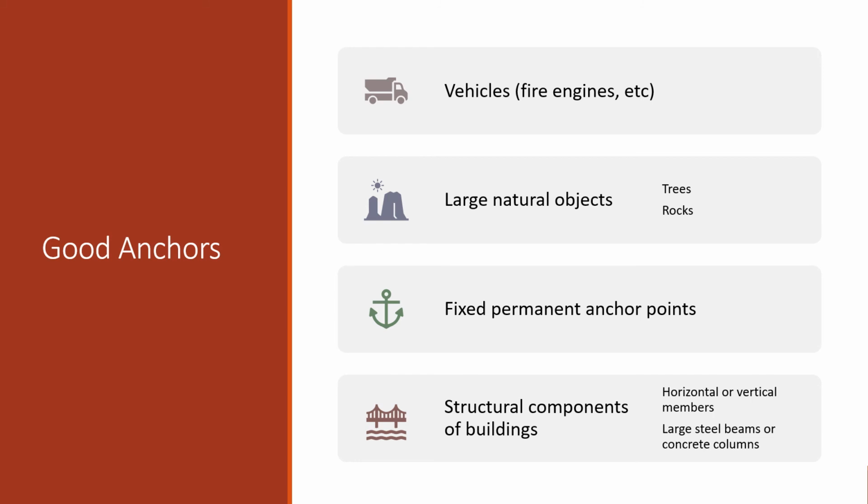Be careful with these, though. Make sure it's a real structural component. Guardrails to keep people from falling over ledges are not structural. Don't use them as anchors. They won't take the load, especially when you have them up like that. You're going to create a moment because you're putting force at a distance away from the line of action. You're creating a moment. You're going to bend them. It's bad. Don't do it. Same with bridge rail. Not good. Watch out for those lighter weight bits of stuff. You want the big, heavy, structural components of things.